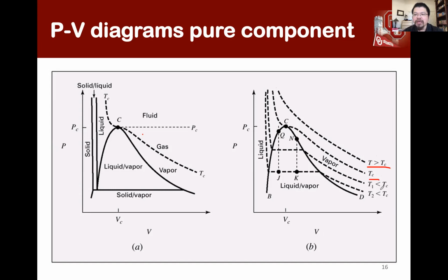And in the past, we had a discussion, say we are going to move the liquid all the way up, right? And we try to understand what would be the change of the system, what is the ratio between the liquid and the vapor. Using the lever rule, we are able to understand what is going on, whether they will disappear simultaneously, or we are going to have a remaining vapor or liquid phase by the analysis.